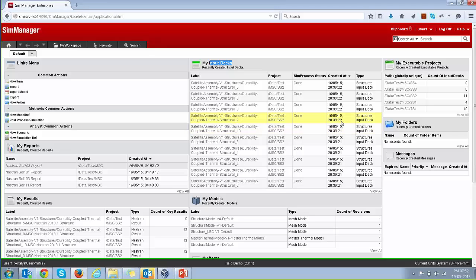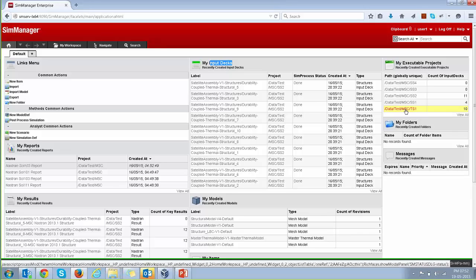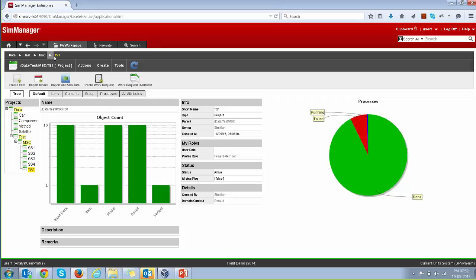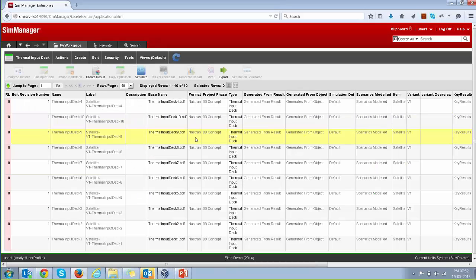by default. So let's say, for example, the thermal analyst has already run 10 different thermal simulations in this project, which is a thermal simulation project. In this context, it could be varying the heat flux because of various environmental factors or various heat loads generated by the circuits. And then he has created 10 different thermal simulations.